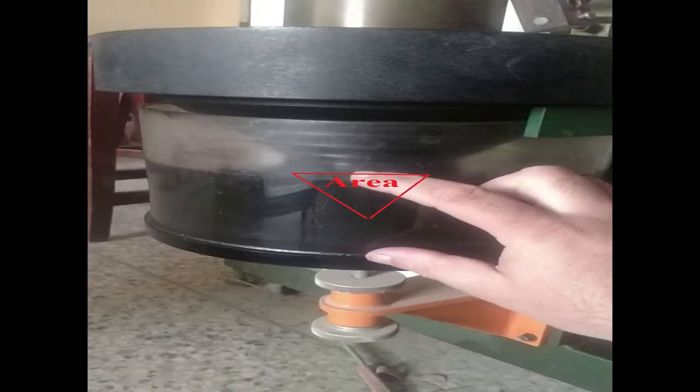The oil container may be raised and lowered by means of thumb nuts beneath, and in the process the area of contact between the oil in the container and the surface of the conical flywheel attached beneath the heavy rotor can be altered. This effectively varies the damping force on the oscillating rotor.